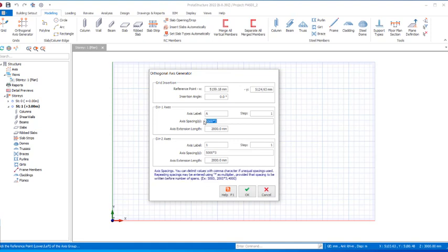All right, so for the horizontal grid lines, we are going to be having 2500 and then asterisk 2 places, and then you have a comma right there. Okay, so what we'll be having again is 4800, just like this. All right, then you asterisk it into 3 places. After you must have gotten this in the horizontal provisions, we will go straight away to the vertical directions of the axis.